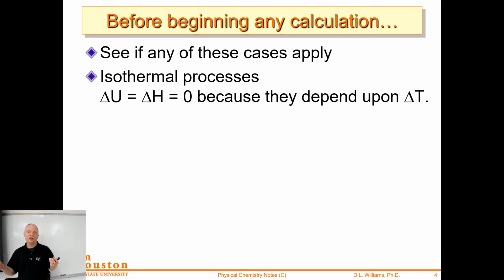And this is stuff you just have to know. I can't help you with this. You've got a sheet of equations on your note card. Which one applies, right? Well, if you were to apply the equation that contains delta T for this segment, you would see that delta T is 0. And so you might waste some time writing all that out, or you could say, by definition, temperature hasn't changed, so I know that delta U and delta H are 0.